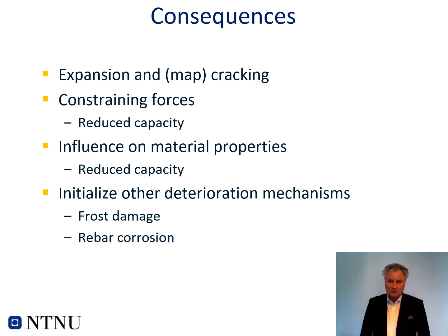But also, what is important is that these mechanisms could initiate other deleterious mechanisms, like frost damage if water is coming into the cracks and so on. And also, when water or chlorides come through the cracks to the rebar, you could get some rebar corrosion. So the AAR mechanisms could also lead to other deleterious mechanisms.